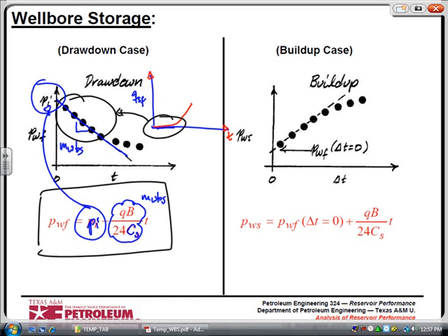The guy in Malaysia had over 100,000 data points for the rate and the pressure before he realized, in comparing the 100,000 data points from the rate taken every few seconds on a Venturi meter to the rate that was proven by means of being shot over to a tank through a separator, which is correct, that there was a substantial difference in those rates. And so he went back and tried to correct the rates. He didn't do a very good job. The pressures, on the other hand, were outstanding. They were measured bottom hole pressures, continuously measured.